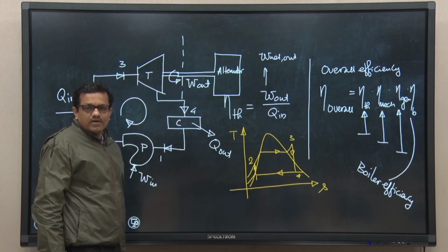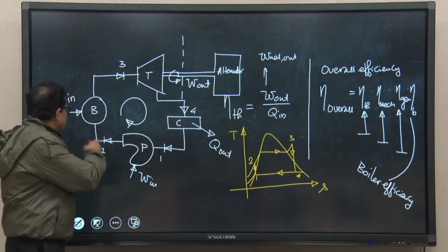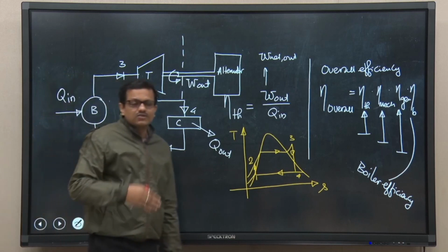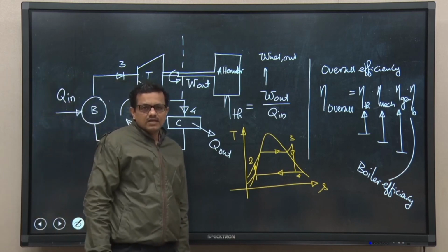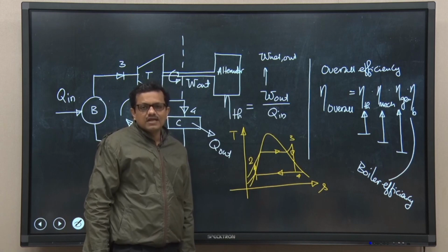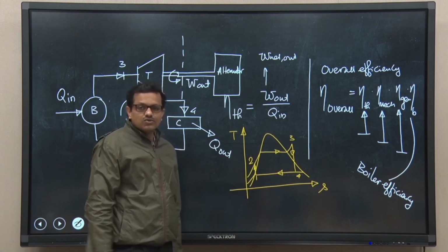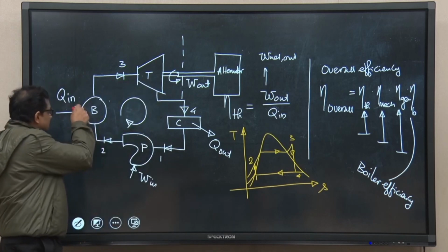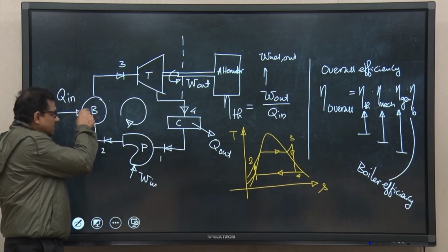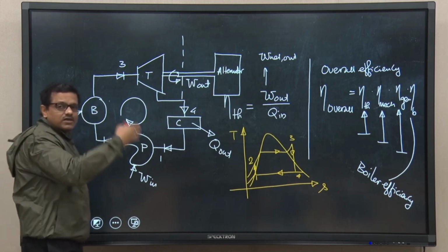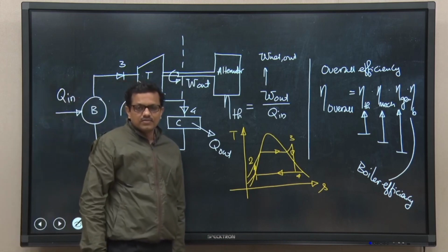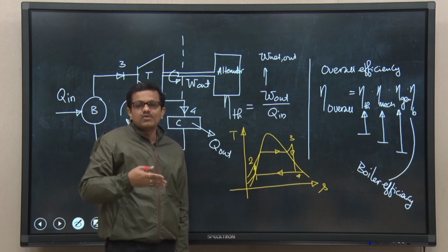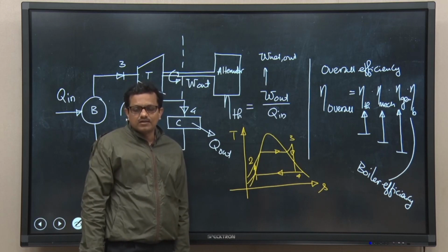Why am I using the word recovery? Because the amount of energy added to the boiler is not going to convert an equal amount of energy to increase the energy of the working substance that goes through the boiler. The energy added to the boiler would be utilized to convert water into steam, there is no doubt about it, but there must be some leakage of energy inside the boiler.